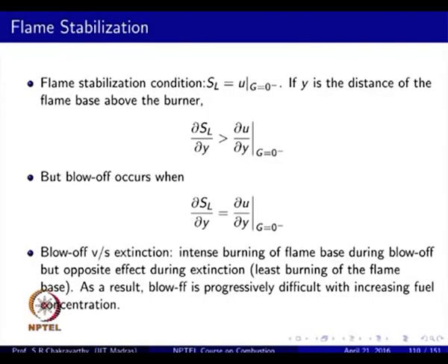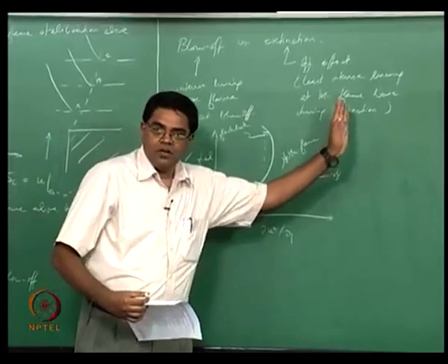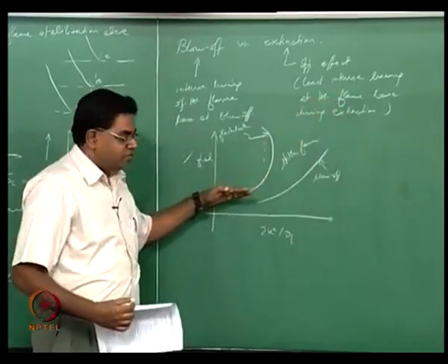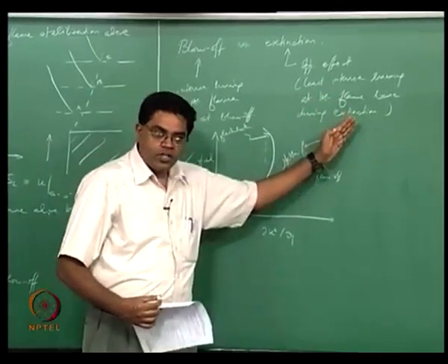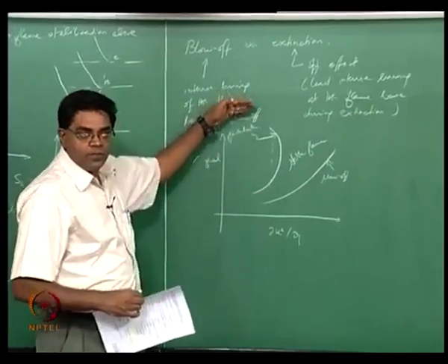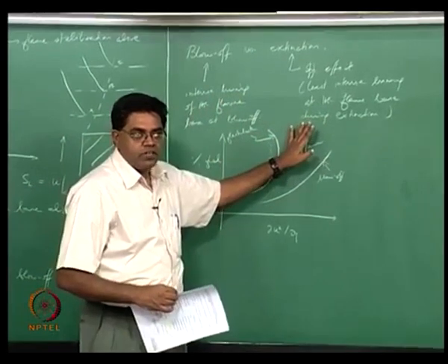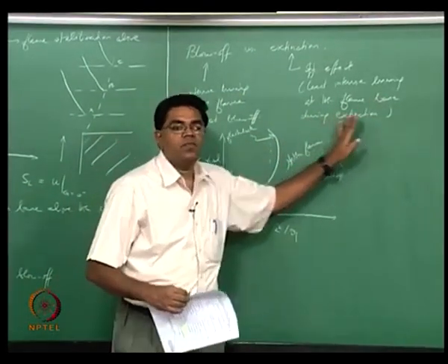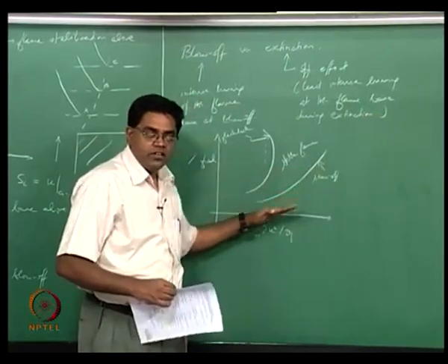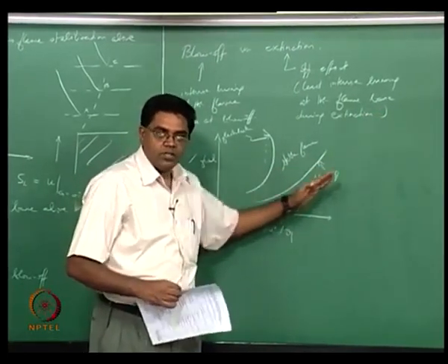That's not the case with blow off. The blow off doesn't look like a non-monotonic curve. It doesn't really curve back, right. So it keeps increasing. What that basically means is, as you are going richer and richer, the flame is going to be relatively indefinitely stable against blow off. That means it's not going to blow off. It's only the lean flames that are actually susceptible to this.